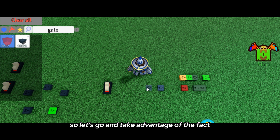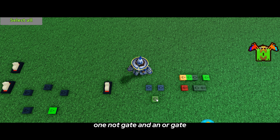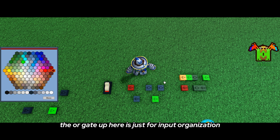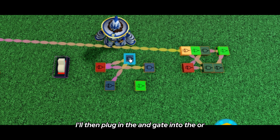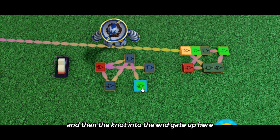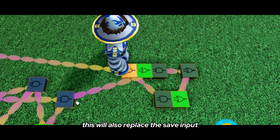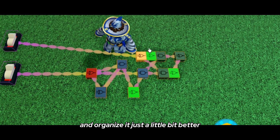So let's go and take advantage of the fact that there's gate delay in the game. I'm going to use 2 AND gates, 1 NOT gate, and an OR gate. The OR gate up here is just for input organization. I'll plug the red input into these 2 AND gates. I'll then plug the AND gate into the OR and the OR into the AND gate, and also connect this into the input. I'll also connect the AND into the NOT and then the NOT into the AND gate up here. This will also replace the save input. I'll just drag this over too and organize it just a little bit better.